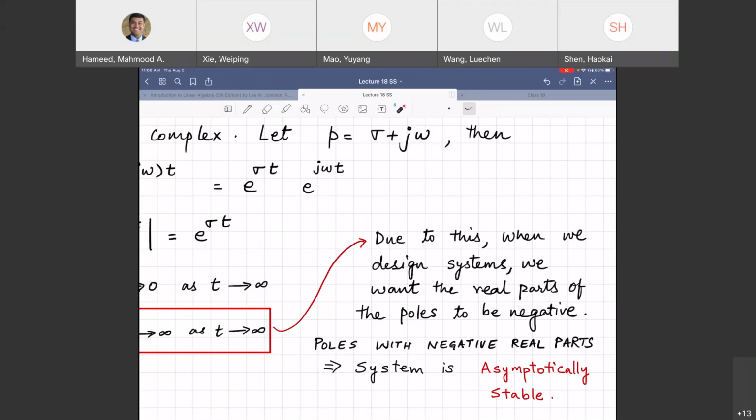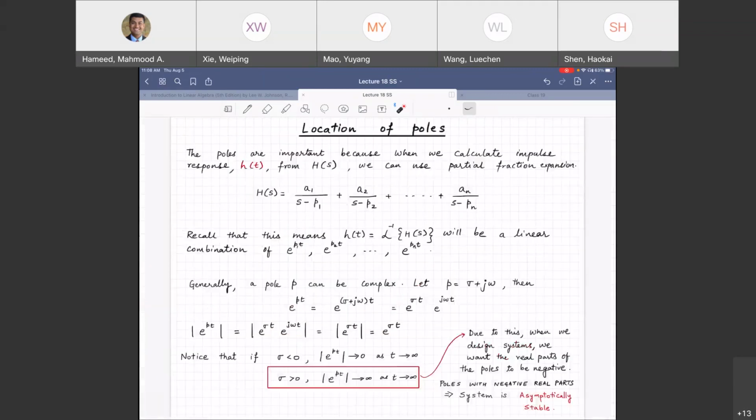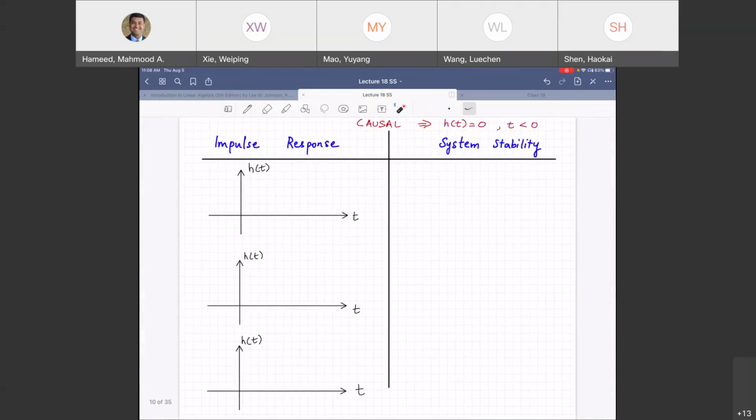So that's marginally stable. For that particular case, I'm going to find that the poles are actually on the j omega axis. But when you have a pendulum, the poles of this particular system are going to be in the left half of the plane, telling me that as time goes on, you will become stable. You will converge.